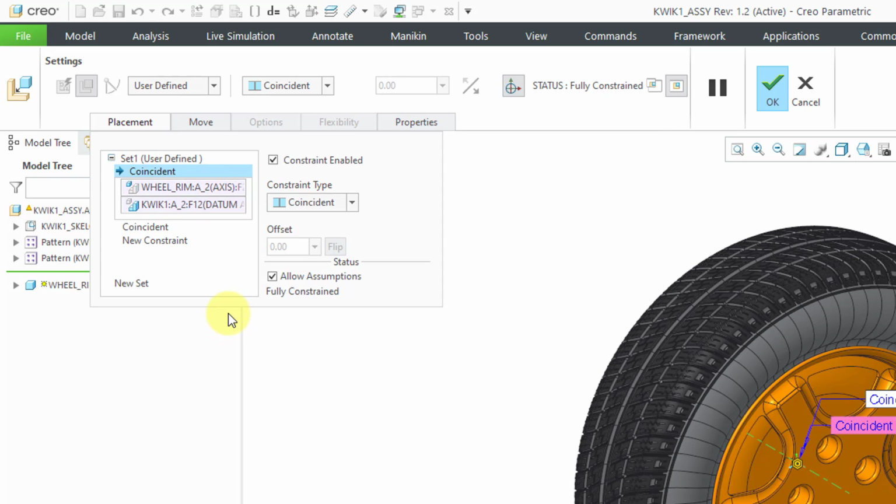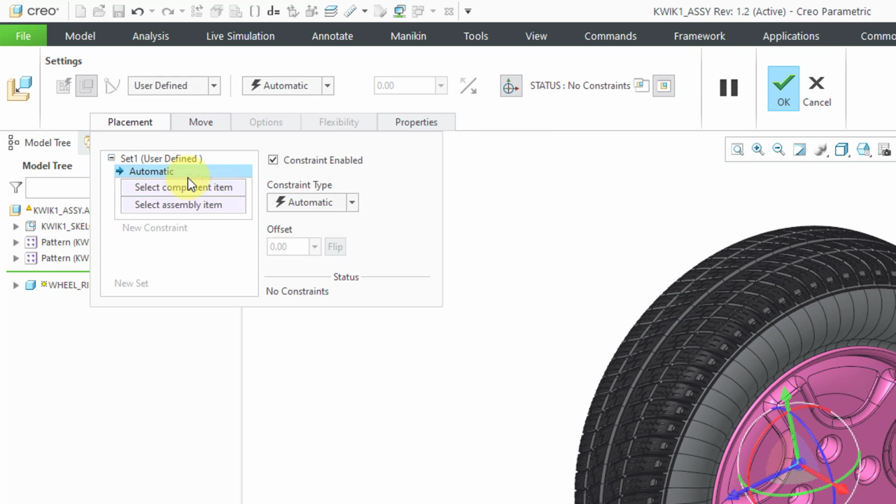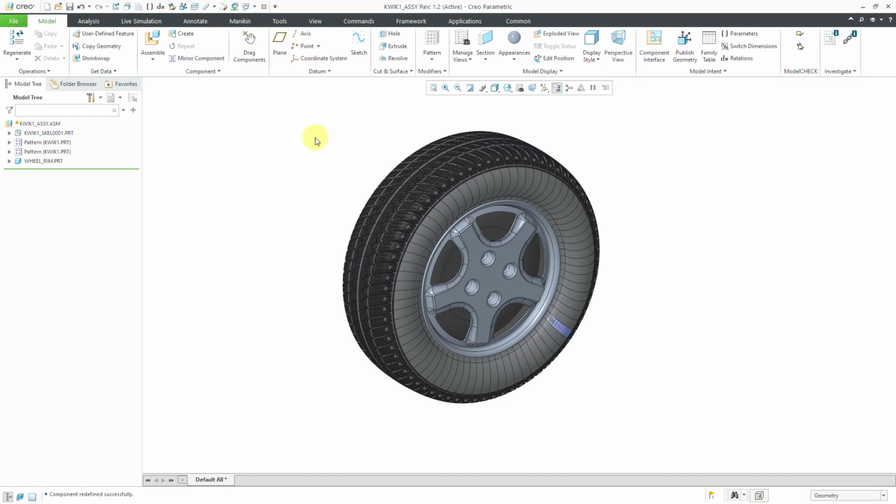Again, this is how people screw up. They go one step too far. They create the part probably in the default location, and then they edit the definition in order to assemble it using real constraints. To take care of it, the easy way is just to delete the existing constraints in the model and change to the default constraint. And here it says fully constrained. For some reason, the part's not changing color, but that doesn't matter.